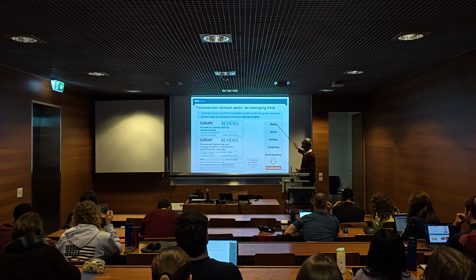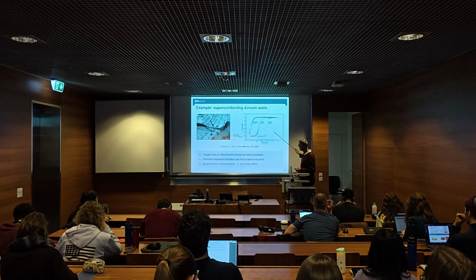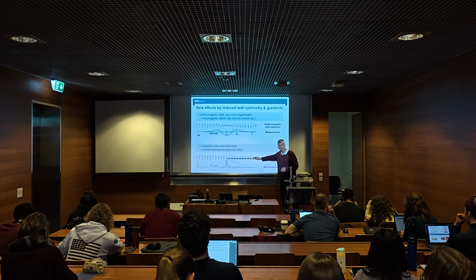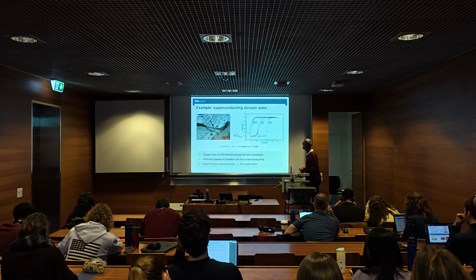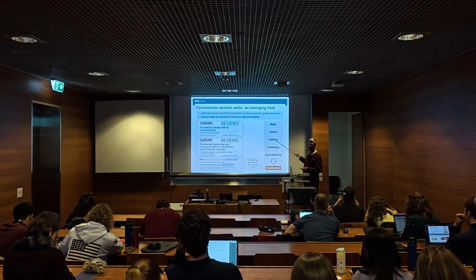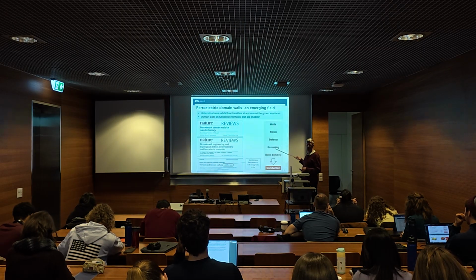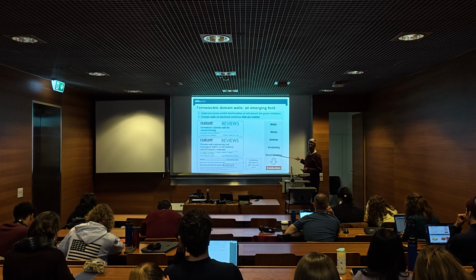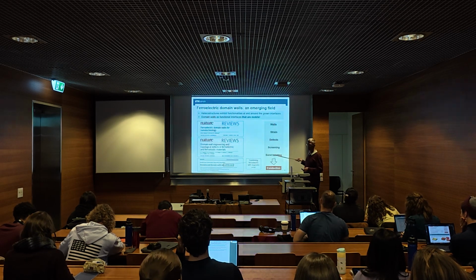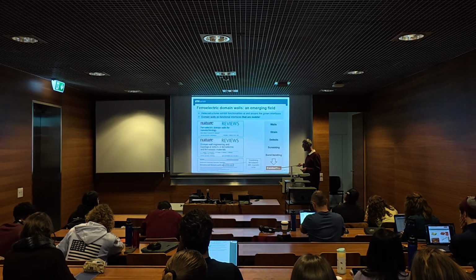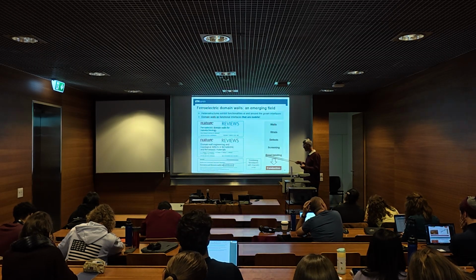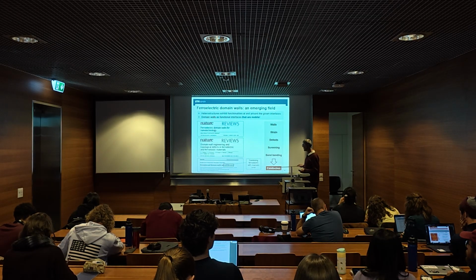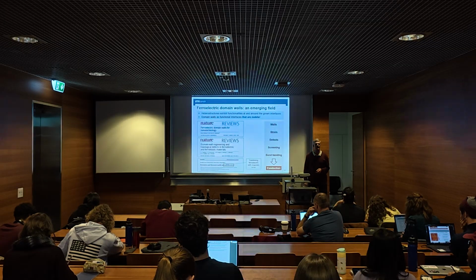If you have a ferroelectric wall, it's strained. Here, look at that. A wall always carries lattice deformation, meaning strain. Strain induces defects in your material. Defects attract charges, and you can screen polarization or enhance it. Then you get electronic band deformations because of the electric field built into your material. And that somehow ends up bending, so gaps become smaller, or you slide around the Fermi energy, so that in the end they have a different electrical conduction.